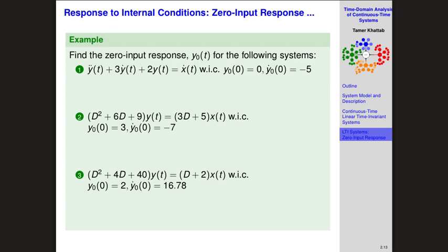In general, again, for a particular system, those modes or those different roots or those different characteristic values represent what we call the resonance response of the system, which means that for those particular values or time constants, or we call them frequencies, when they get represented as cosine or sine functions, the system can sustain the input going through it without any additional push from the input side, which means that if you excite the system at that particular frequency, it can keep on going and it might actually break down.